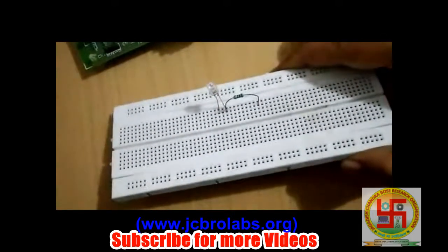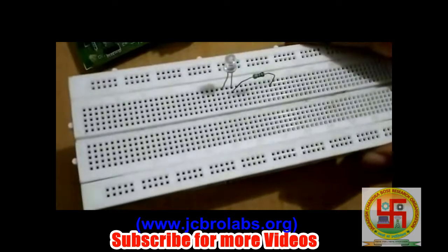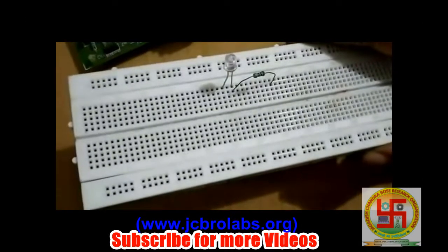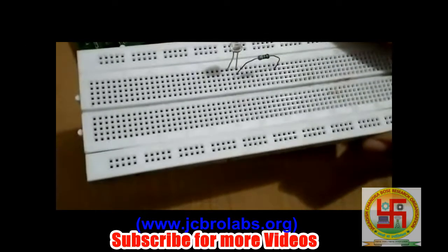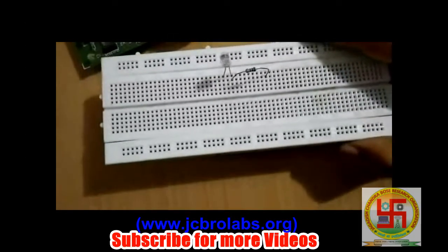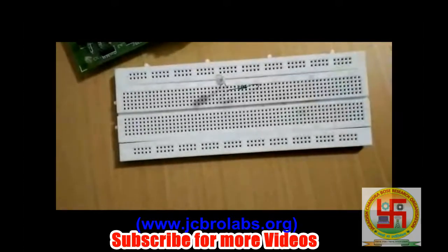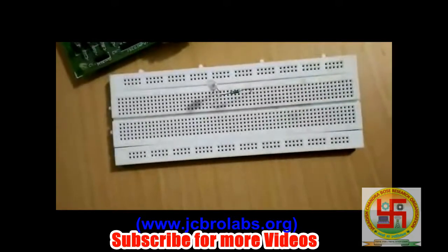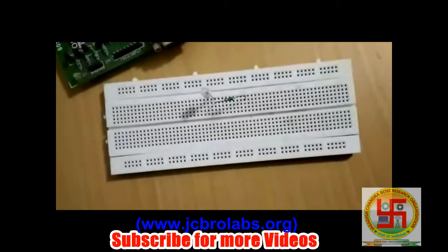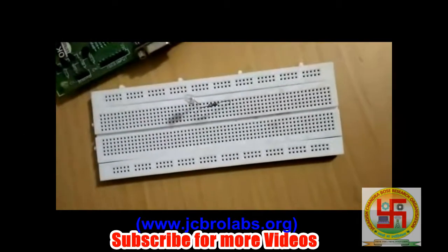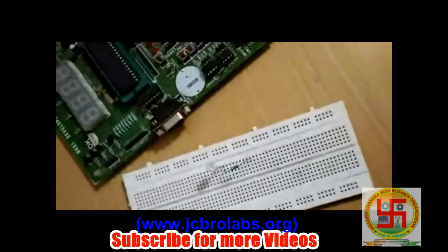Let's have a look. The LED's negative leg and the resistance leg are in the same shorted line, and the other pins are in other lines, so that they are isolated from each other. Now let's connect the power supply. We are providing the power supply for this circuit from this board.